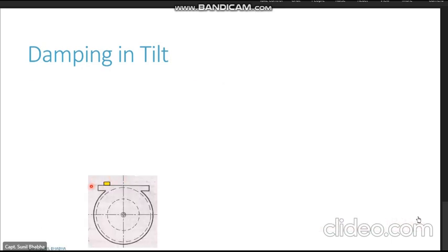Which we saw in the earlier slide, it shows the rotor, the spin axis pointing towards you. You are looking at it from the south end, the north end of the spin axis going into the screen. We have the casing represented by the solid black lines, and we have a flat portion on top of the casing. We have a small weight, 17 grams to be precise, fitted on top of the casing in the plane of the rotor, but slightly offset to the westerly direction.